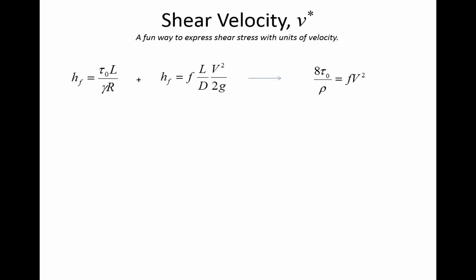So it's just rearranging the shear stress expression, which we already had, and substituting that into the Darcy-Weisbach equation. So if we're combining these two together, then one thing we remember is that for a pipe that's flowing full, the hydraulic radius R is diameter divided by 4. And so if you combine those together, it may not immediately be obvious where that 8 is coming from, for example.